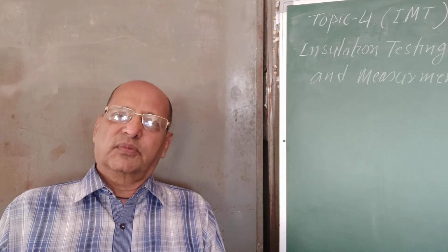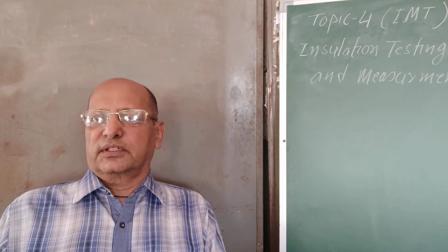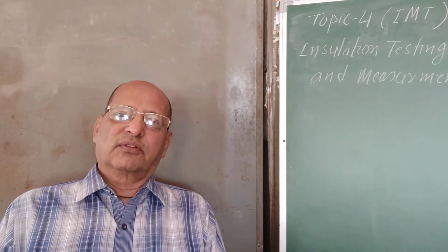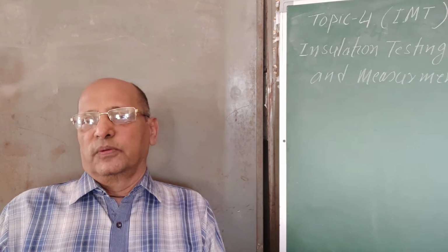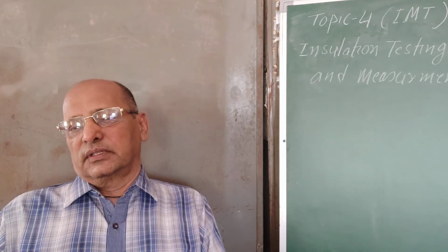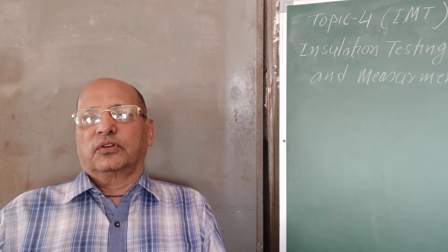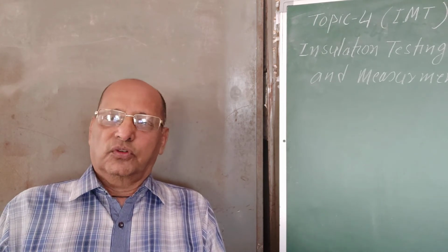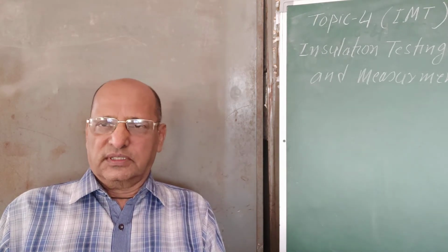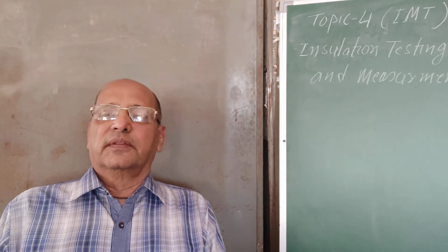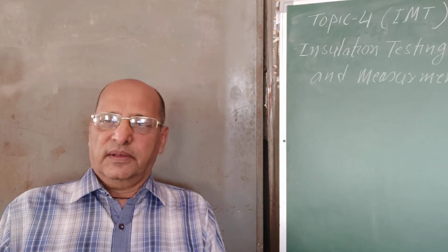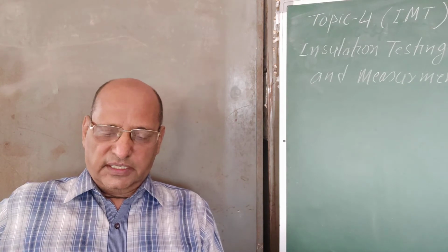So the quality of the oil insulation deteriorates and its dielectric value also goes down. In that case, for reclamation, you have to go for filtration of the oil. So this is one method of improving the insulation resistance of the insulating oil.